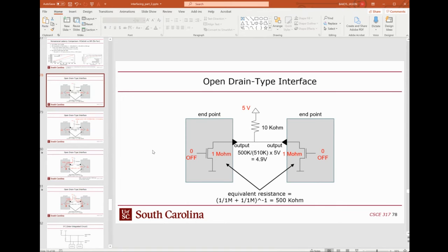So I mentioned that UART has a ground wire, but SPI doesn't have a ground wire as part of the channel, right? But in fact, it would have to, right? Because whenever you do any electric communication between different devices, they need to have a common reference, at least when doing single-ended signals, when you have one bit per wire.